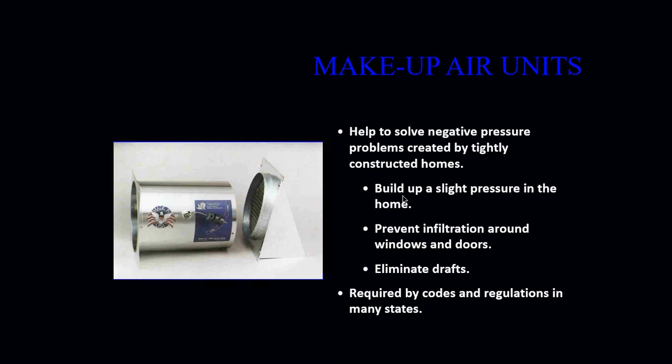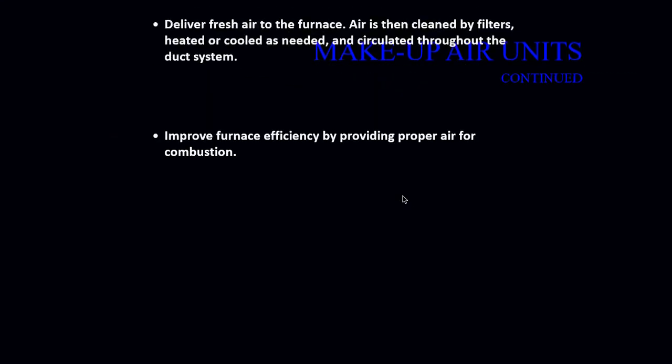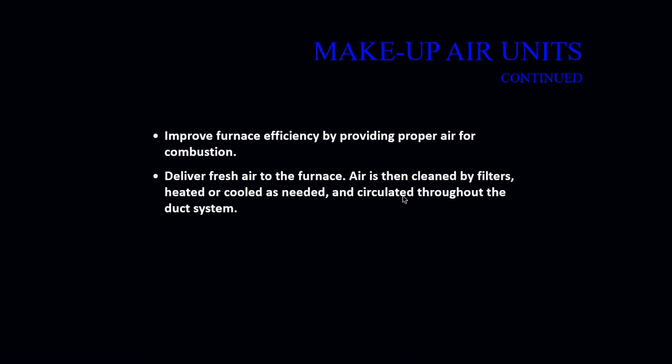Okay, you may also run into makeup air units as well. These help solve negative air pressure problems in tightly constructed homes. Okay, they build up a slight pressure in the home, which prevents infiltration around windows and doors and also eliminates draft. Some are required by code and regulations in many states. It also improves your furnace efficiency by providing proper air for combustion.